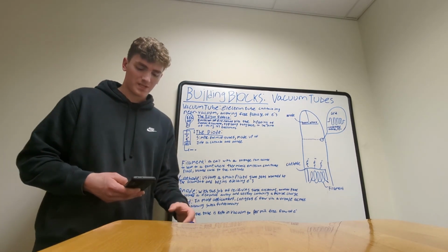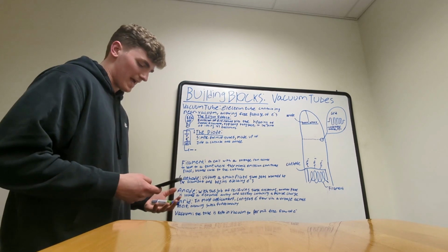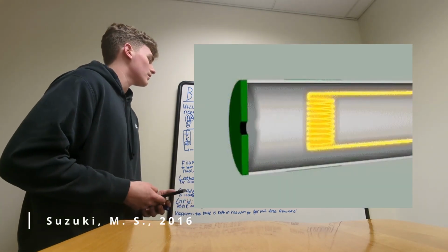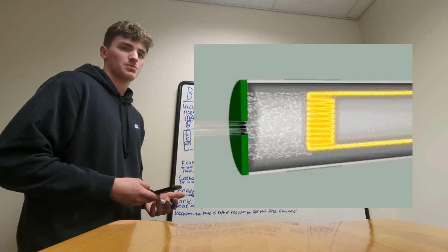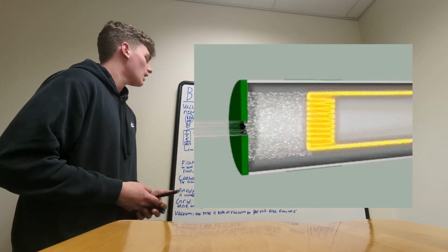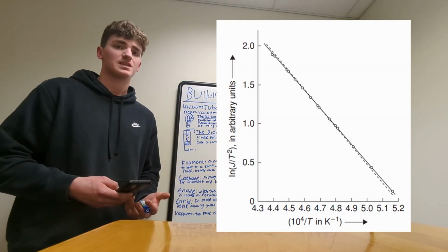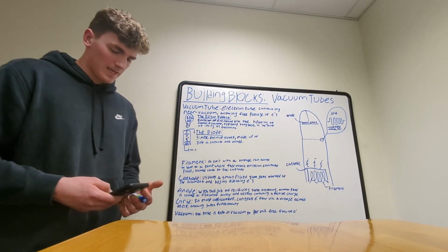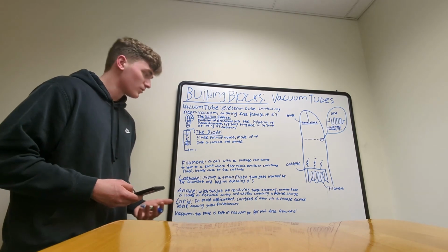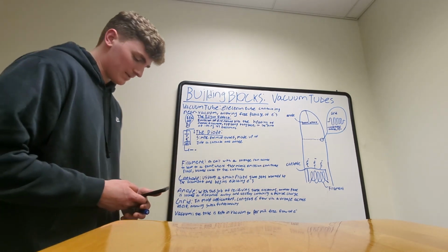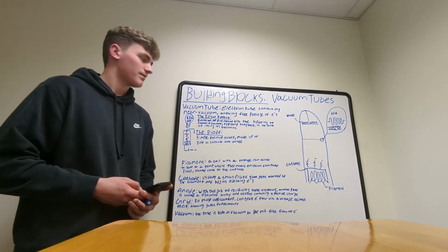Going off of that, the most important piece of knowledge floating around all this is known as the Edison effect, or thermionic emission. It's essentially just the emission of electrons via the heating of a metal filament, typically tungsten, or something coated in tungsten at least, to the point of getting so hot that it loses electrons. This threshold is normally around 1,000 degrees Kelvin. This was discovered from the most basic application, the incandescent light bulb, when it was found that it emits electrons when the filament was heated up enough.